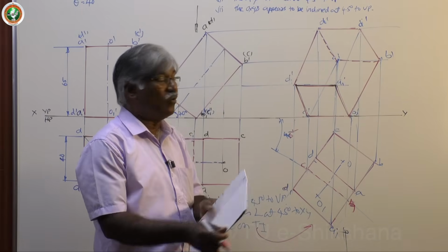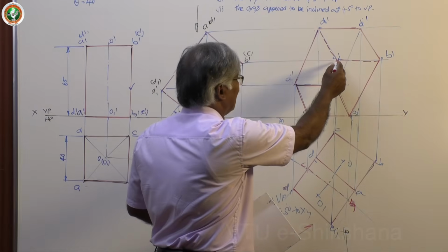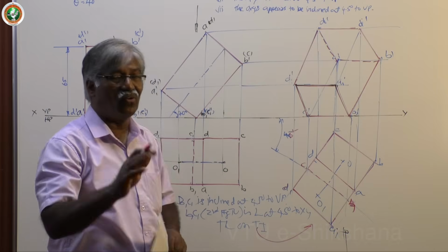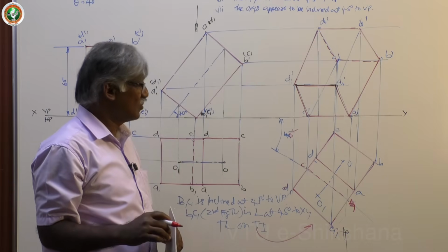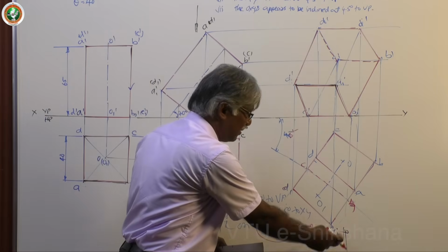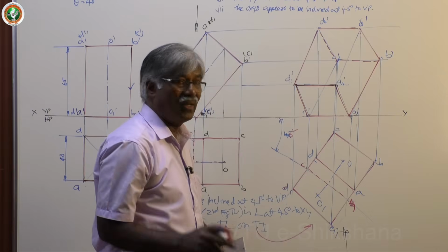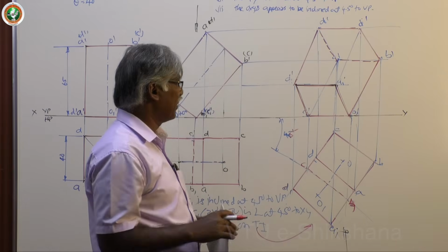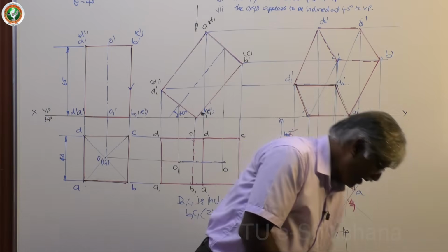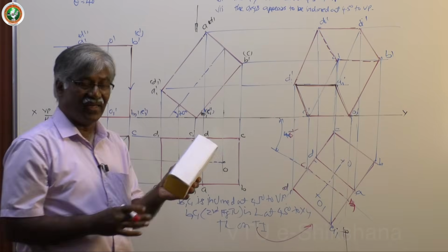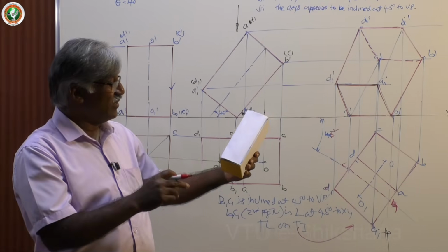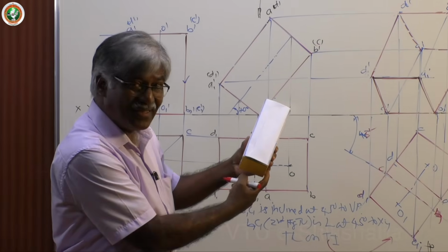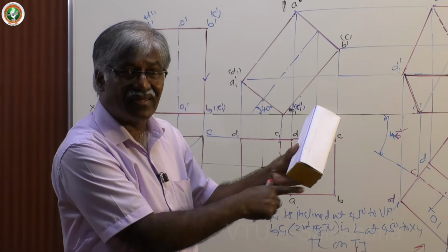Now, how to complete CC1, DD1? Only two are left. How to do it? One may say it is nearer, it is visible, and all. No. Then I will tell you the very basic fundamental concept. See, here I have the visible key surface. And in this case, you can see this longer edge. You cannot see this longer edge. Why? It is behind this surface.